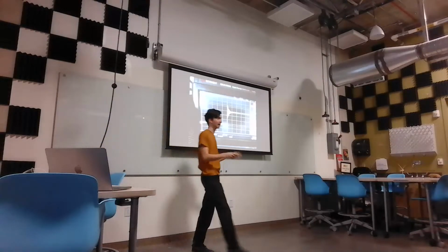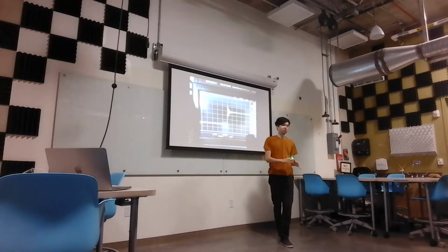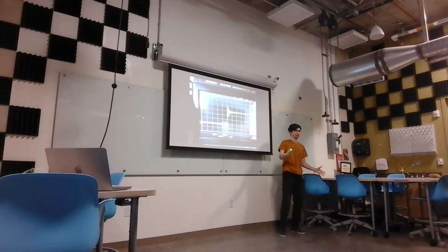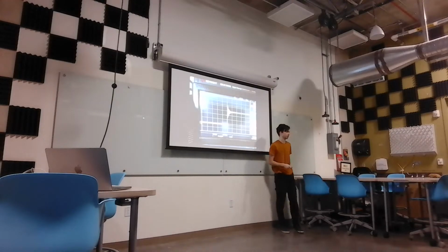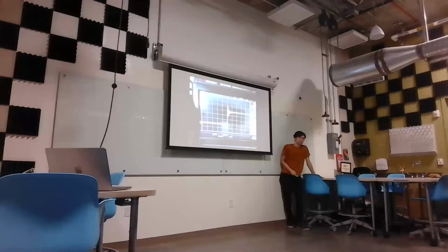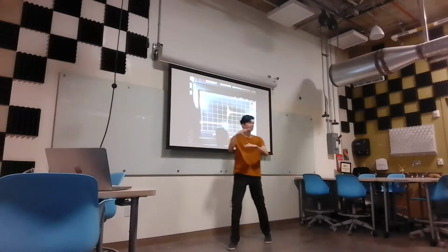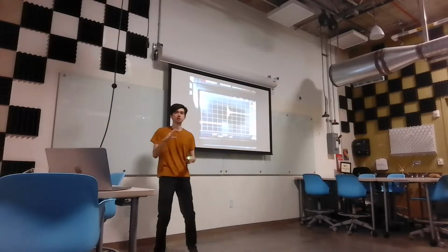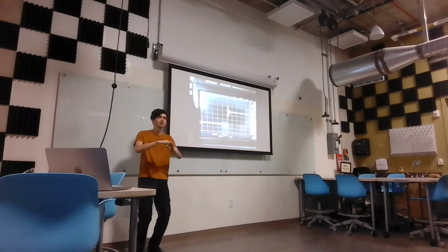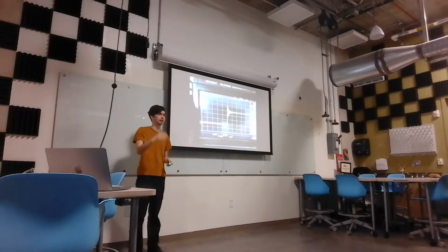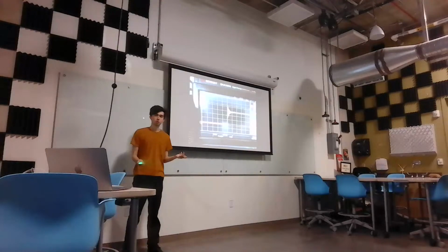Sick. I now know that I have technology to make things switch at reasonable speeds that are way bigger, because these are really tiny. That's why they're able to switch so fast. So I just put a resistor on the gate for the MOSFET. That makes it turn on slow, because the gate of a MOSFET is like a capacitor. If you just have a capacitor that's super low, it instantly charges, but the resistor there is a slow charge. Resistor and MOSFET, it's like an RC. Super cool. That fixed it.